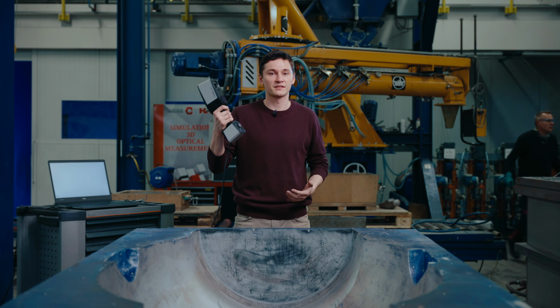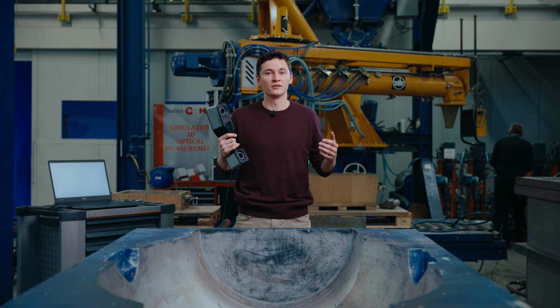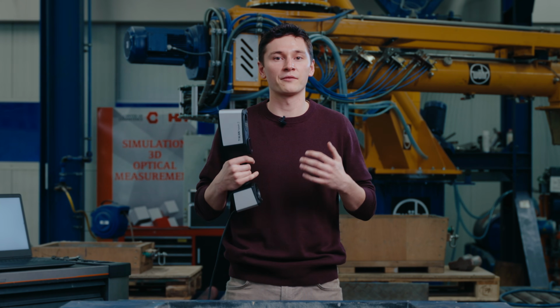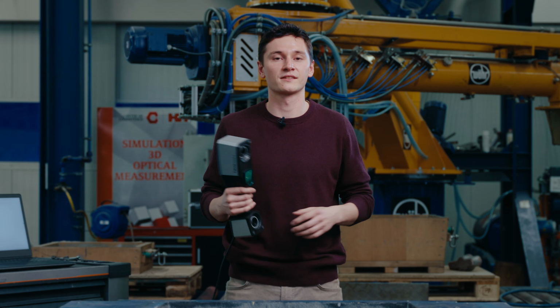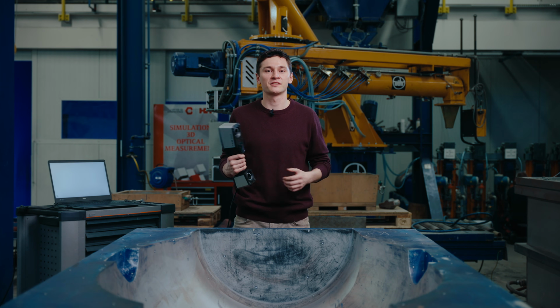We do this by first scanning the mold, resulting in a 3D mesh. This mesh can be used in the ZEISS reverse engineering software to create a CAD file from it. Once you have a CAD file, you can recreate the manually changed mold and you have a reference for your future inspection projects. This way we make sure that our new parts are cast according to the changes which have been made. Let's take it and make it!